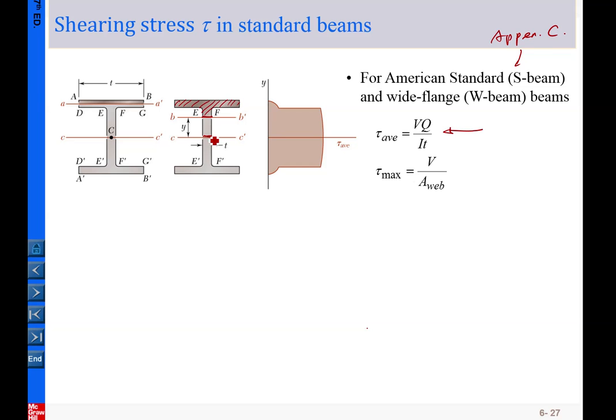And for the maximum shear stress, you can again apply the concept. It happens here at the middle, because for tau equal to VQ over It, whenever we want to find the maximum, we try to maximize this parametric term. In this term, V is constant and I is constant, so the two you wouldn't be able to change once a cross section is selected.